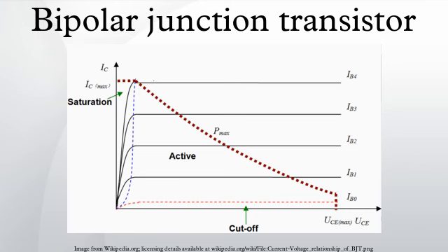It means the transistor is not letting conventional current go through from collector to emitter. Reverse active: base lower than emitter, collector lower than base, reverse conventional current goes through the transistor. In terms of junction biasing, in forward active, the base-emitter junction is forward biased and the base-collector junction is reverse biased. Most bipolar transistors are designed to afford the greatest common-emitter current gain, βF, in forward active mode.